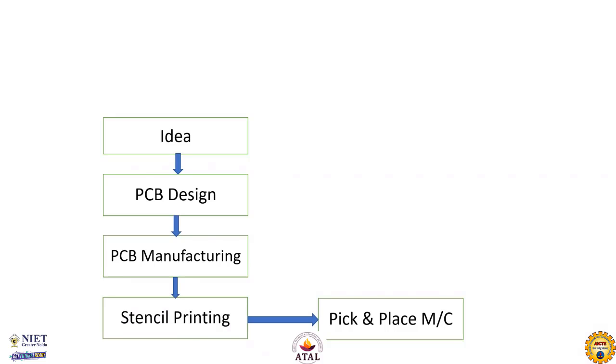Then what the pick and place machine does is, all the components of electronic devices come as feeders in a tape, a small plastic tape, and through the feeders this machine picks the components and places them on the PCB automatically. This is one of the nice facilities which you can use. And then once it is done, the PCB where the components have been assembled,